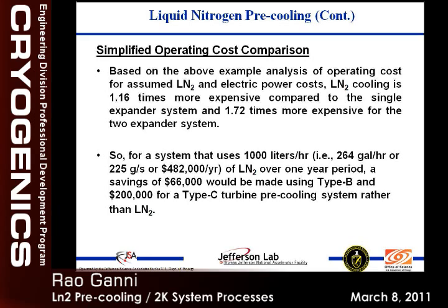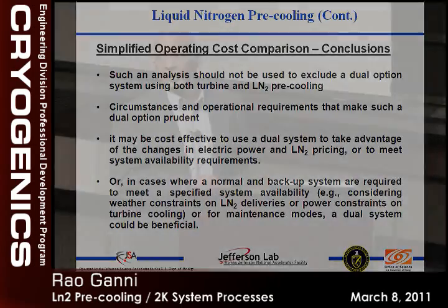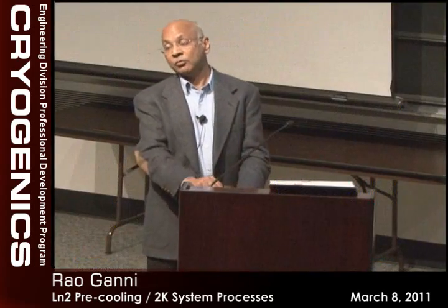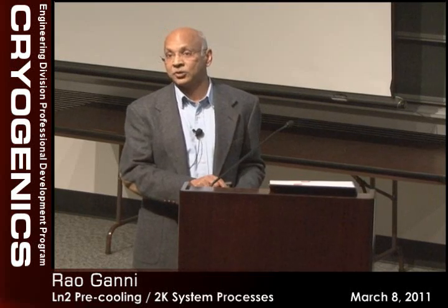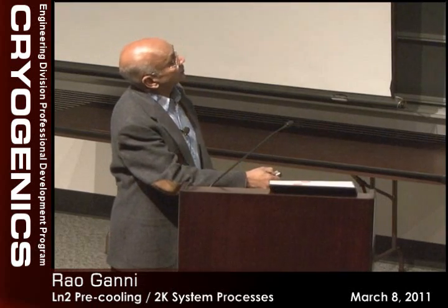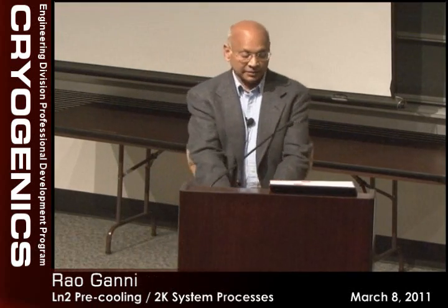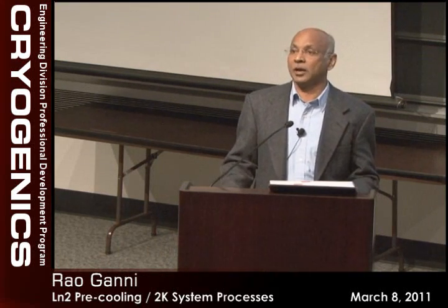So basically, unless it is planned from the beginning, it is not that easy to eliminate nitrogen once you start the plant. People ask me, should we go back and change it? But the nitrogen usage has been well distributed all over. And for the amount of nitrogen we use on site, it still doesn't justify having our own nitrogen plant here, because the plant is too small to be efficient. So that's basically the nitrogen pre-cooling and why we have 1 or 2 trucks showing up on our site every day.